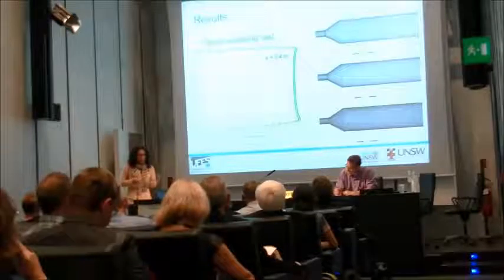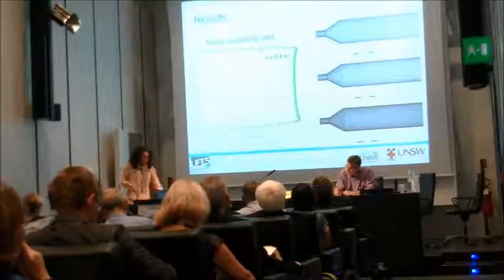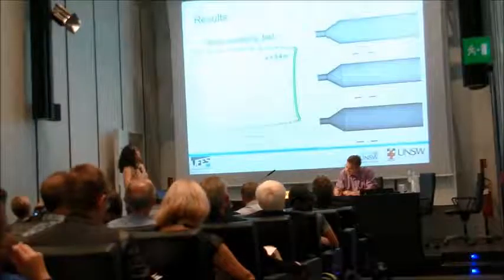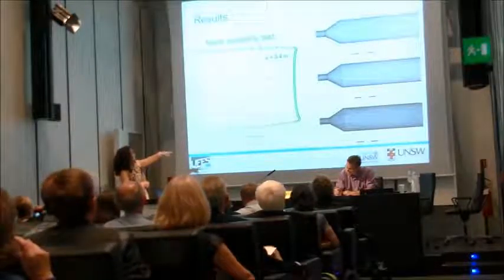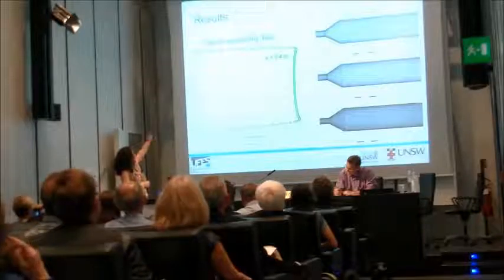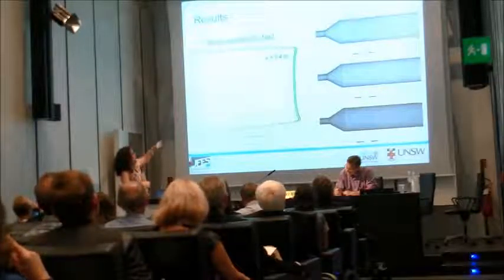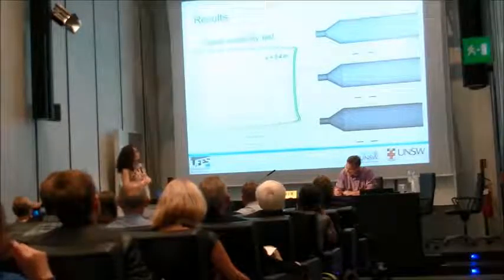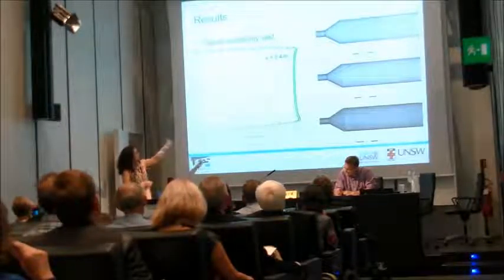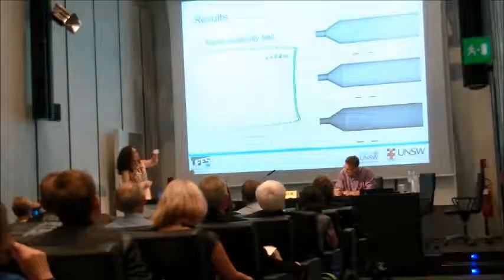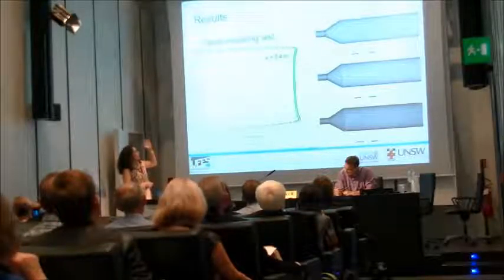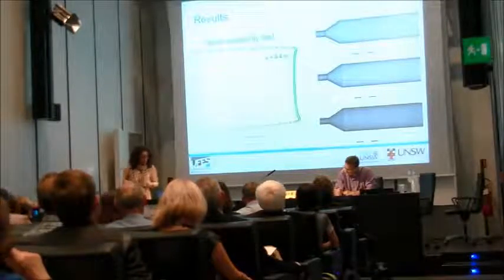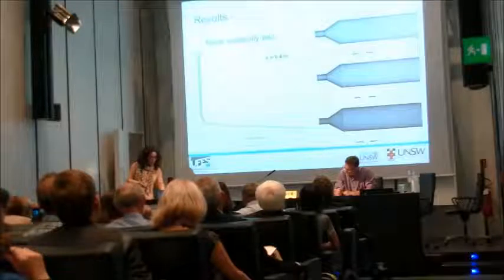So we could use any of the meshes, but we decided to go for the... sorry, let me go back here. This is velocity against height inside the wind tunnel at a distance of 0.4 meters from the inlet. The different lines are the different meshes we used, and you see visually there's no difference. In numbers, the difference was really, really small.